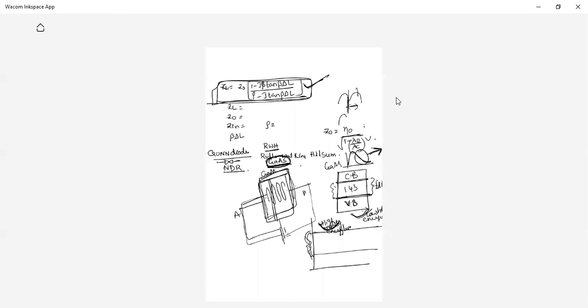Initially, he took a gallium arsenide slab and applied a potential. When it exceeds a certain voltage, he observed oscillations in that slab. That effect is called the transferred electron effect or Gunn effect. And what are the characteristics?